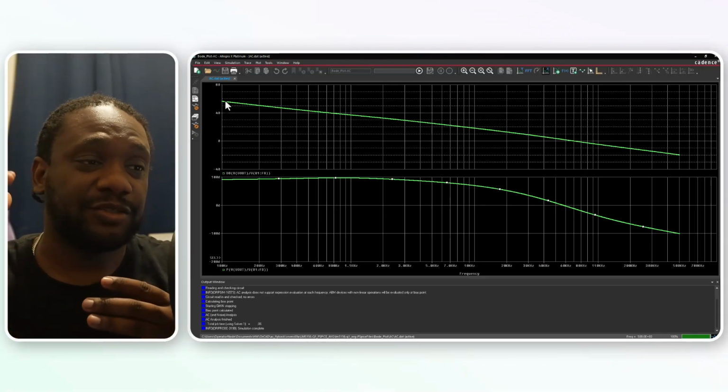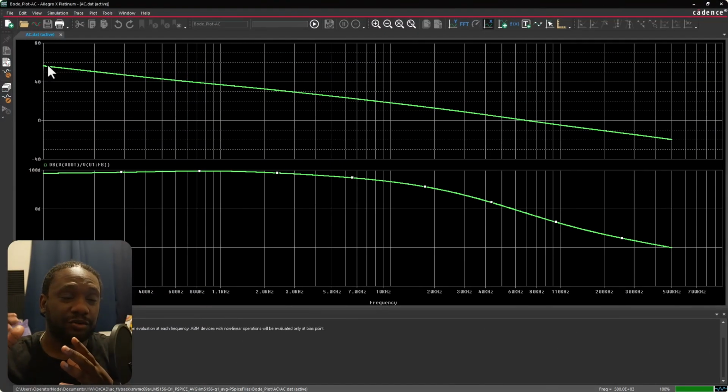As long as we are operational, we want to amplify that error and notice when it's there, so the controller can execute a certain gain to get our V out. Basically, what the gain does is multiply or amplify and say, hey, we have a certain error. We're going to put out this much gain to increase the duty cycle, or the on time, for the switch. So we're going to keep the switch on a bit longer.